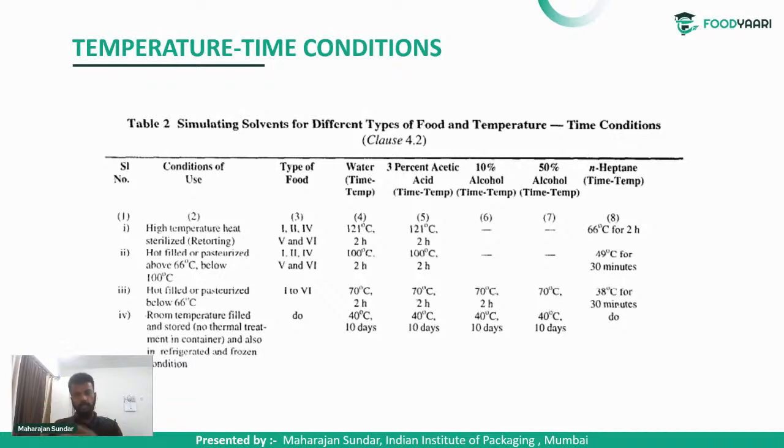Before pouring the migrated simulant in the beaker, we have to weigh the beaker, so that we will get the beaker value. Next, after adding and drying the simulant from the beaker, we will get an extraction concentrate.